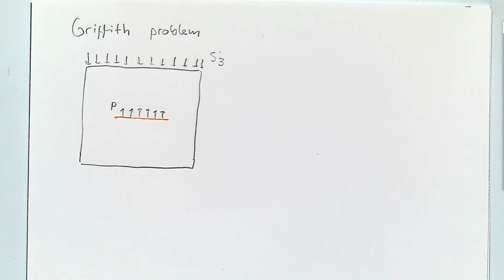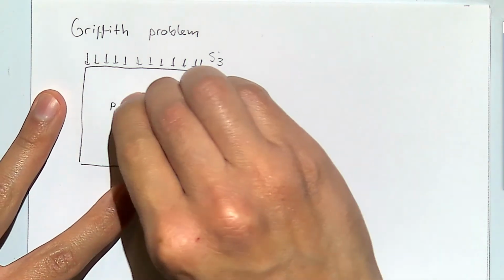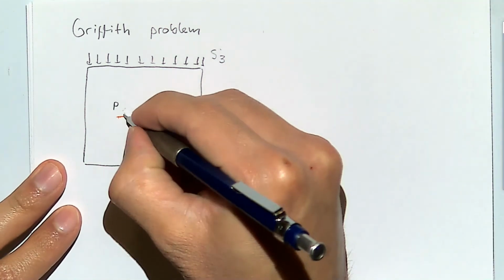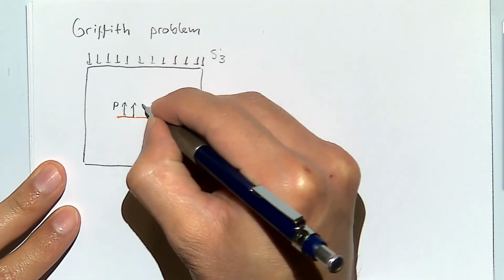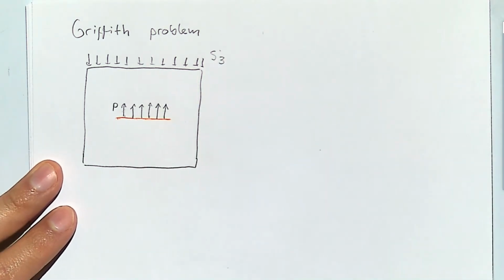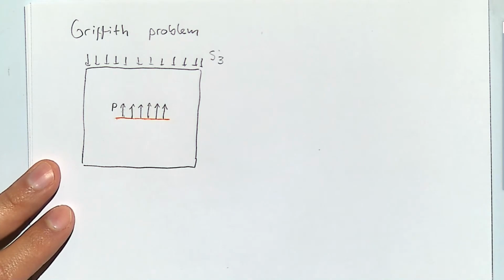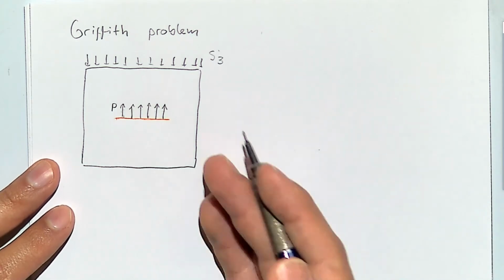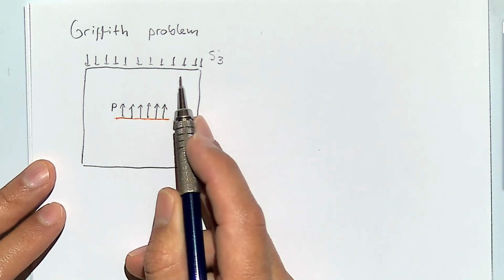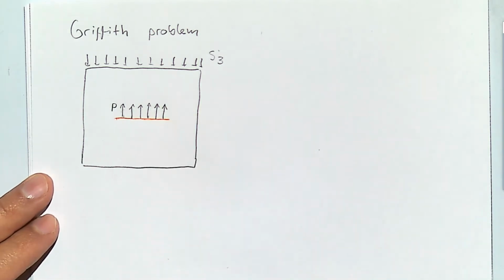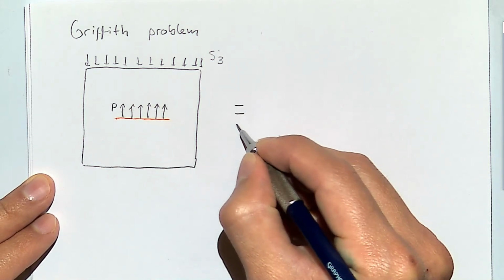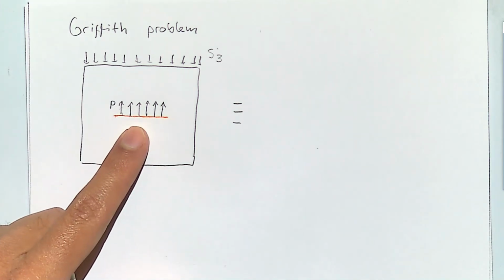And for that, the medium in which this fracture is, it doesn't have any pores, doesn't have any permeability, any nothing. So the total stress is just going to be an effective stress. And as I was saying before, for this fracture to open up, the pressure inside the fracture should be larger than the total stress, because otherwise it wouldn't have enough support on the wall of the fracture in order to open up.